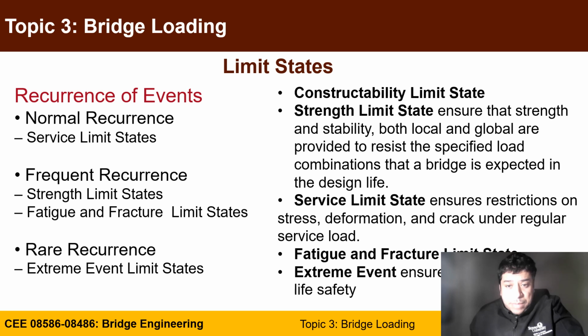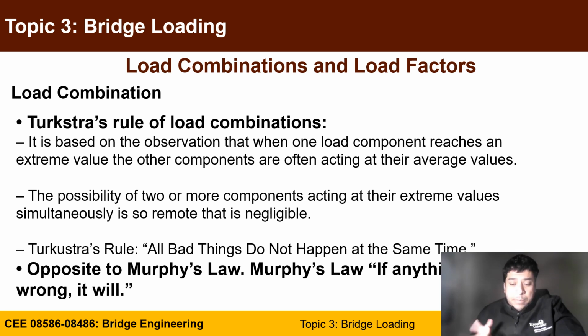Back to the limit states: constructability limit state, strength limit state, service limit states, fatigue and fracture limit state, and extreme events. Limit states, load factors and load combinations are really one subject that should be taught together. So load combination. You have a rule of load combination, by which we mean that not all the bad things will happen at the same time.